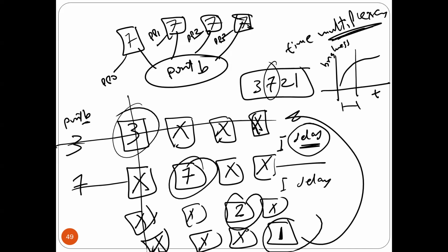Okay, that's one thing. The other thing is, if I make this delay long, you are going to see flicker, because there is a long time. So again, if you write your program and you see flicker, as you will see in the video right now, that means you have to make the delay shorter. Is that okay, guys? You can try 5 milliseconds, 3 milliseconds, 10 milliseconds, and see what's going to happen.